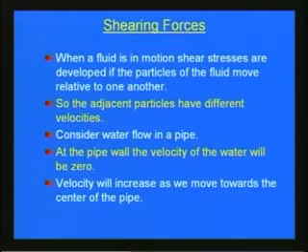Now, in the beginning we discussed a fluid getting deformed with respect to shearing forces. So, shearing forces are very important in fluid mechanics. When a fluid is in motion, shear stresses are developed if the particles of the fluid move relative to one another. Since the fluid is moving, layer-wise, if you consider a section between the layers, there will be shearing force or shear stress.